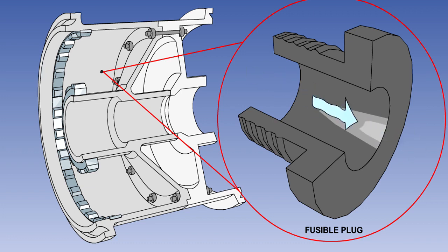The important points to be taken from this lesson are related to the fusible plugs. Remember that they are fitted in the wheel rim, and they protect the tyres from explosion due to overheating by releasing the gas in a controlled manner if an excessive temperature is reached.